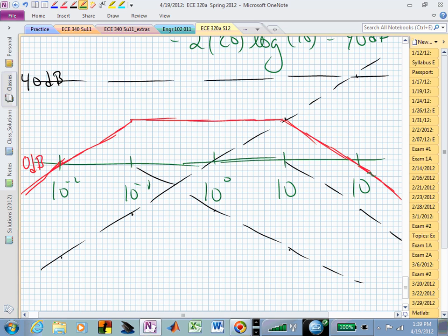And if it's going plus 20 dB, you know you have 1. Then you say, oh, it flattens out at 0.1. Oh, that means I was going plus 20 dB, now I'm 0, so I must have introduced a minus 20 dB per decade slope. That corresponds to a pole. And that pole must have happened right at omega equal to 10 to the minus 1 or 0.1.